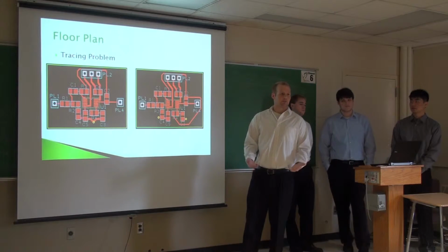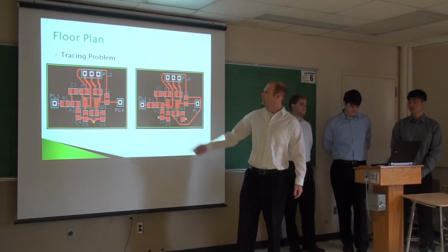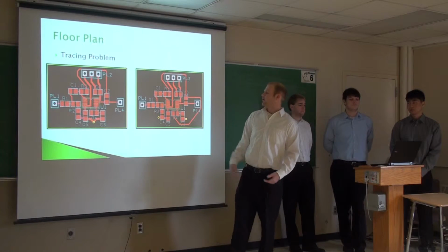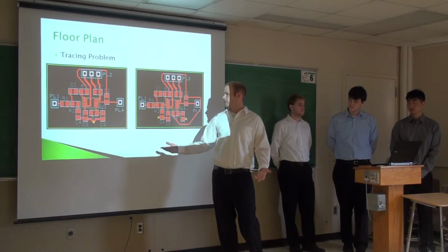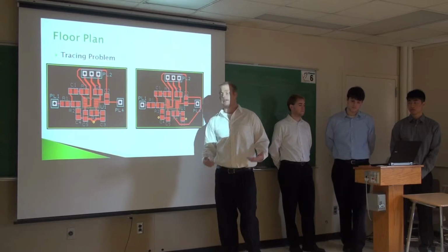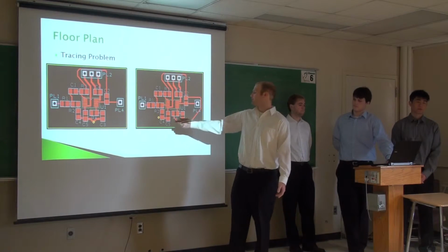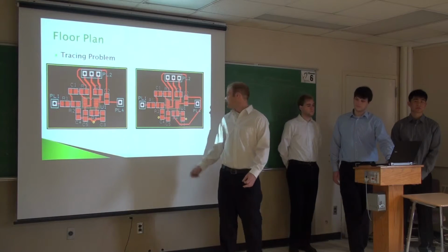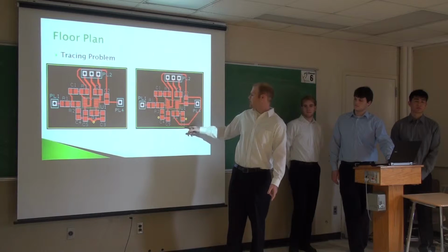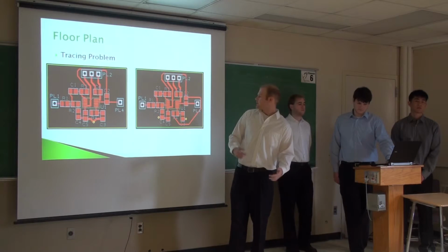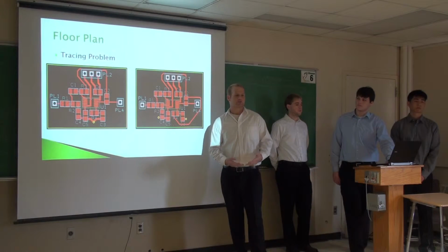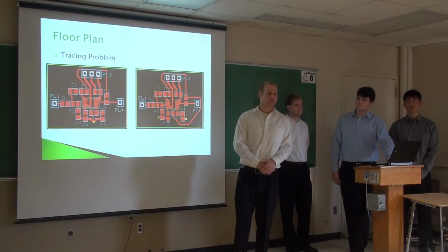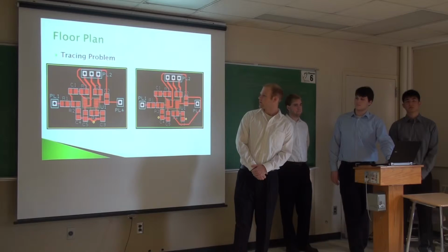So here's an example of a problem you might encounter when you are tracing. Say you want to connect the top of C2 of the node all the way to this R4. You couldn't because there's a ground in the way. But since we have the entire bottom level as a ground, we can put a ground to the left here, a ground to the right, ground out C4 and C5 and C3 on the right. We can make a long trace around our output to R4. Generally, you want to avoid using long traces because the longer the trace, the more impedance they'll have on the board. But in this case, for a 2-layer board in this circuit, it's probably the best design.